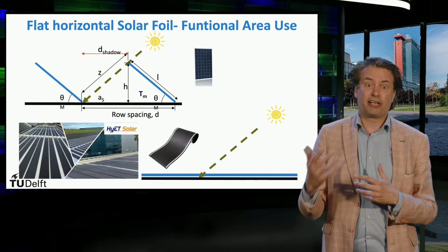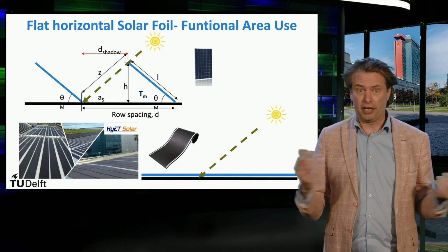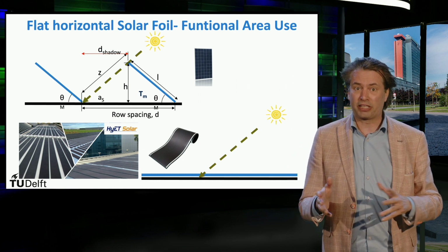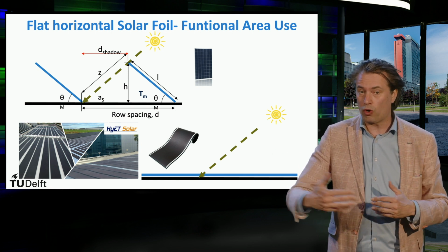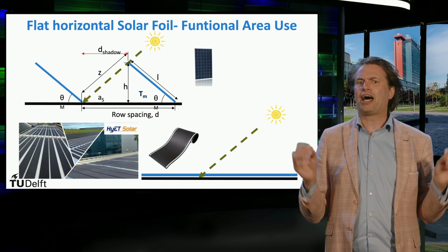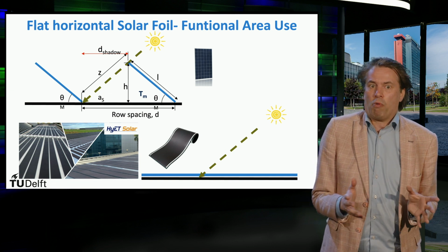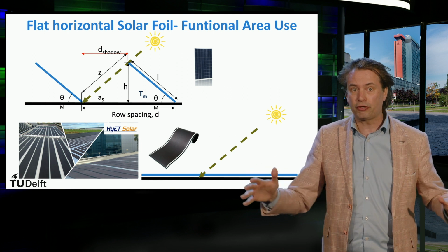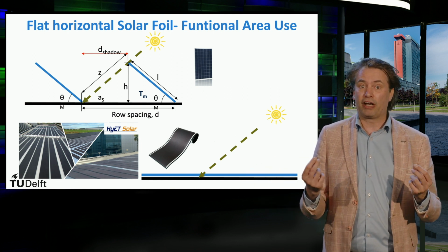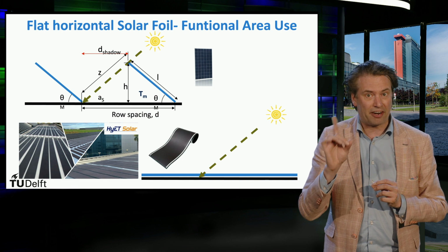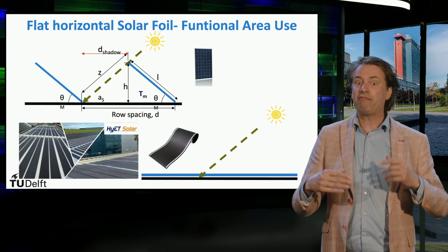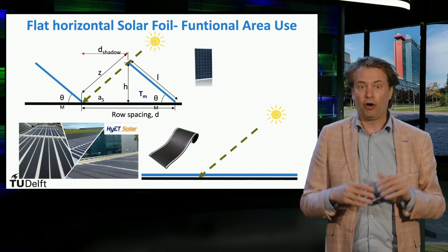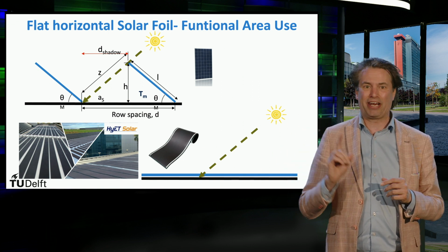Money can be saved as less mounting material is needed. In addition, the modules do not need mutual spacing and are less sensitive to mechanical stresses, which means installers can walk over them. Although these types of module products might have a lower module conversion efficiency, due to the high ground cover ratio realized, the total yield of electricity per functional area of roof or facade might be even higher in reference to PV systems of glass encapsulated modules on the same functional area.